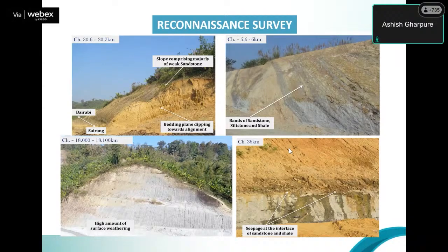You can see surface weathering happening. And in the right bottom slide, if you notice, the water is coming through the joint of sandstone and shale. Shale being impermeable and sandstone permeable, that's where you expect the water. How you can use it in your designing is that you even plan your weep holes across this joint so that you can actually take maximum water out. We see the practice of weep holes being specified 1.5 meters center to center. Actually, if you can plan and put them across these layers from where the water is coming, they will be very effective. Next, please.